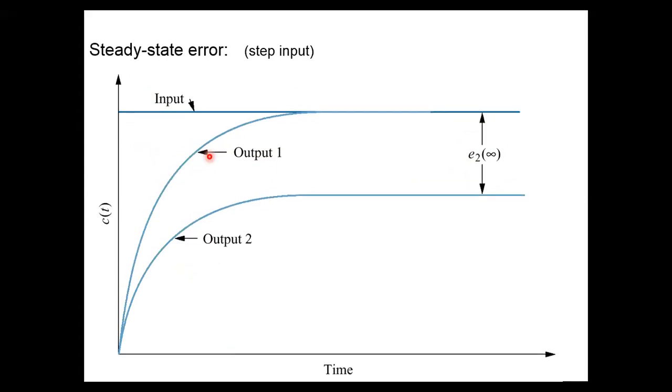Since we are concerned with the difference between the input and output of a feedback control system, our discussion is limited to stable systems only, where the natural response approaches 0 as time approaches infinity. Unstable systems represent loss of control in the steady state and are not acceptable for use at all.